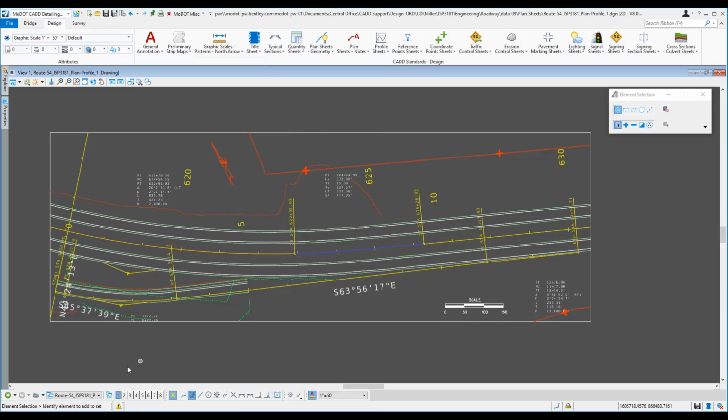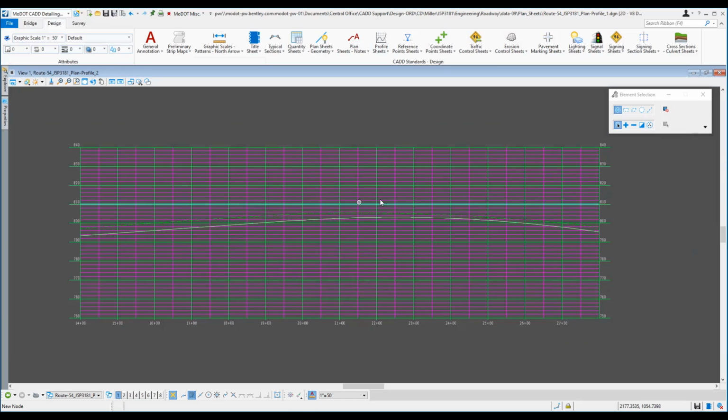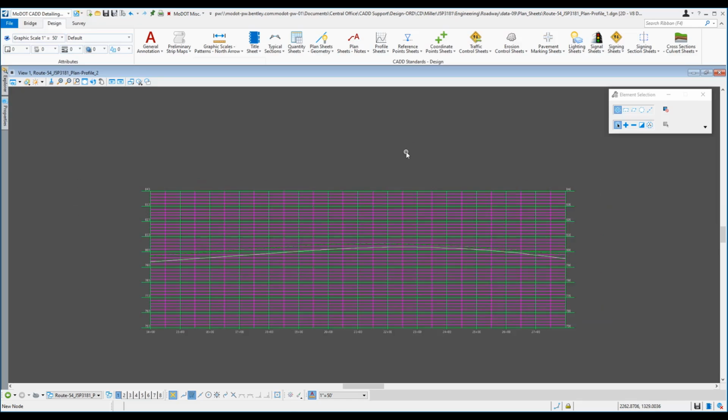So we added those two pieces of information, but I want to look at my profile and look at the profile drawing. And if you go down to the bottom left, you've got these view commands down here as well. And you've got this model selector. And I'll go to the second grayed out paper. It doesn't have drawing on it, but you can tell by the grayed folded piece of paper. If I pick it, it brings me into my profile, and I can do whatever I need to do in here. Add a note, add any information, curve data, or whatever I need to do in here.